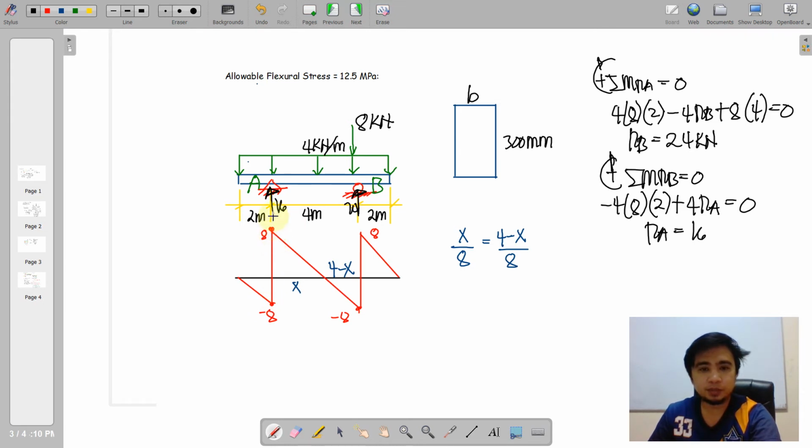And then again, we are going to deduct here 4 by 4, or that is 16. So 8 minus 16, that is negative 8. Again, there will be a push here. But before we take the effect of this push, let us consider the counter between 24 and 8 at joint B. If we deduct 24 minus 8, that will yield a positive 16, an upward 16.